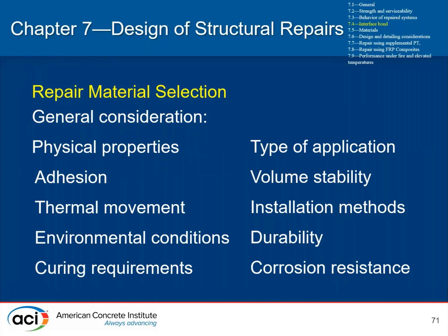So again, that's a very important part. I think a very helpful part of this code with respect to practitioners is helping people understand that the bond is an important aspect. The testing and use of interfacial reinforcement where necessary can be very important for providing that continuity between repair areas and the existing structure.